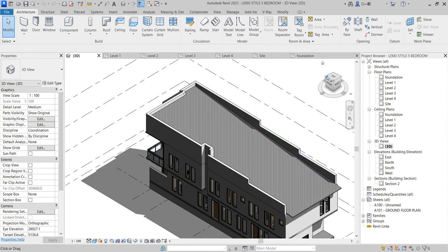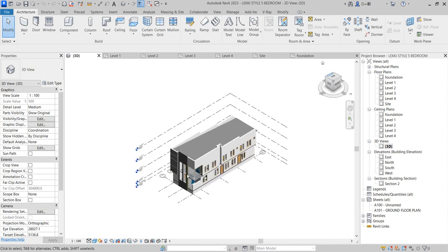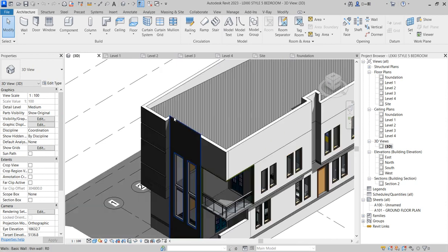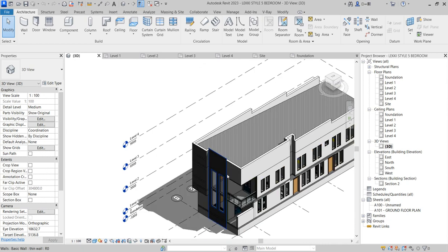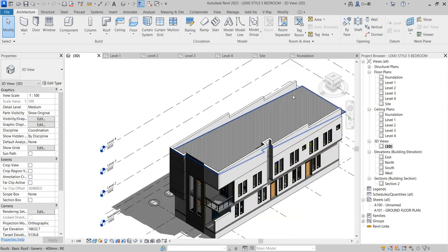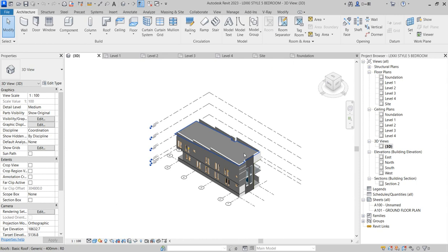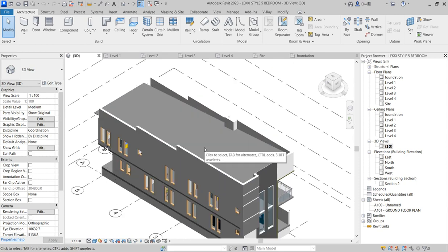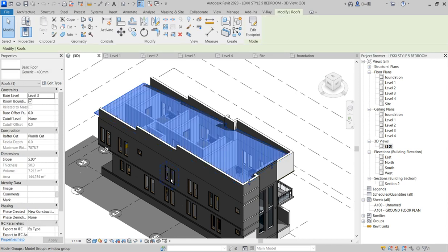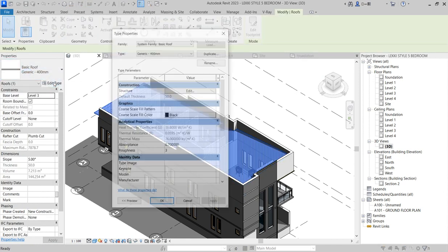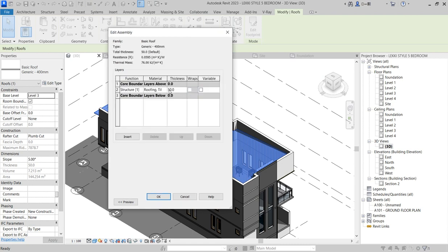So we want to modify this elevation and create a beautiful aspect that will withstand the test of time. Now, the first thing is this roof. Anytime you click on this, you have all these straight vertical lines going straight up without giving any reference to the slope of the roof. Can you imagine? So the first thing to do is to correct that. I'm going to do that by clicking on it, then you say edit in place. Edit in place, go there and edit this part.